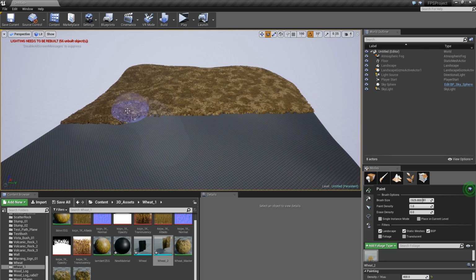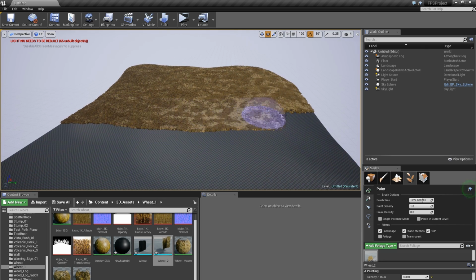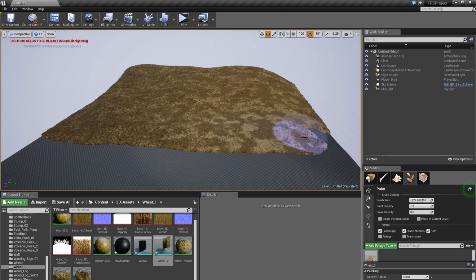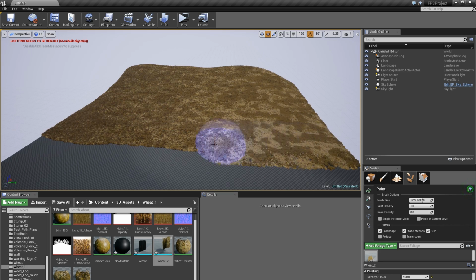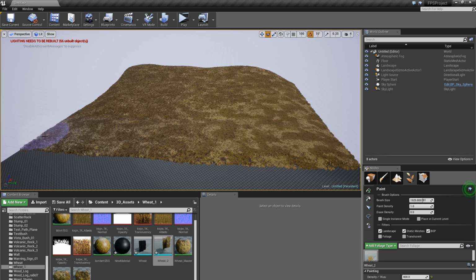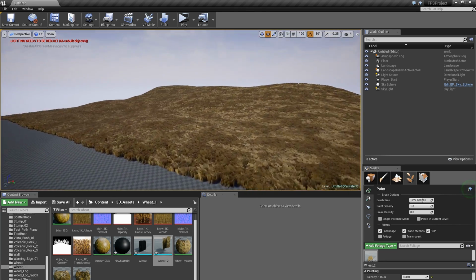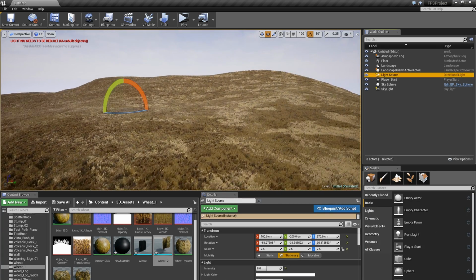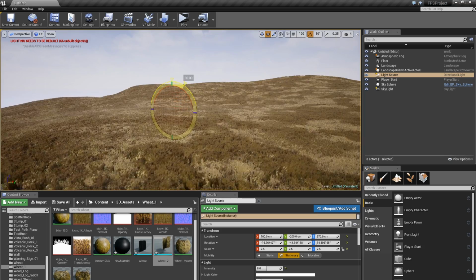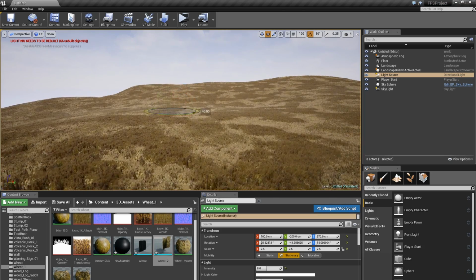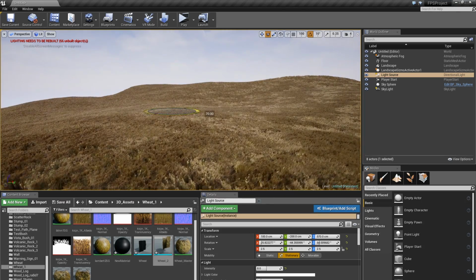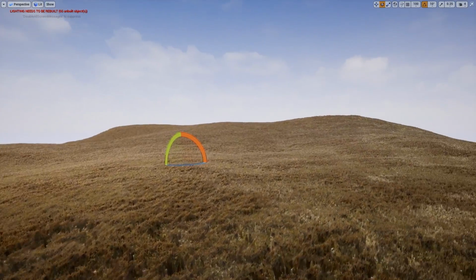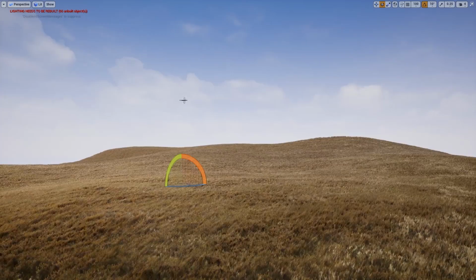You can, of course, use a lower density. You can reduce the poly count. You can use a lower texture resolution, cut off more of the opacity map, or you could just make a smaller area in which to use this effect. So I'm pretty happy with this. So let's go in here. Let's tweak the lighting a little bit because we pretty much already got the result we were after. I'll just rotate this around, set it something like this. Maximize the viewport. And there we go.